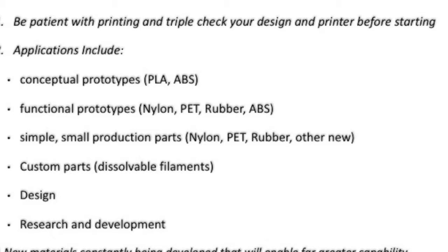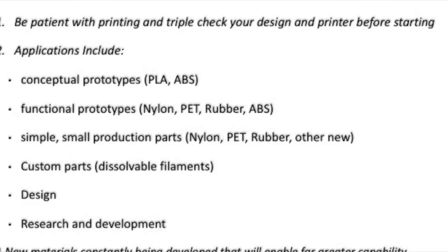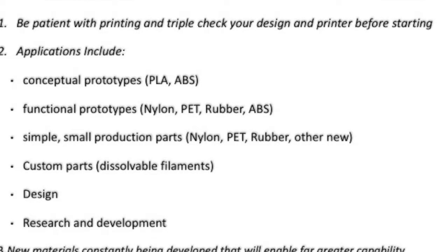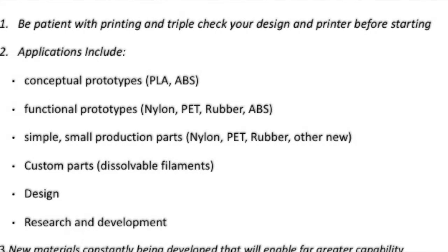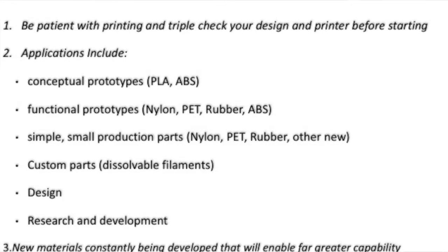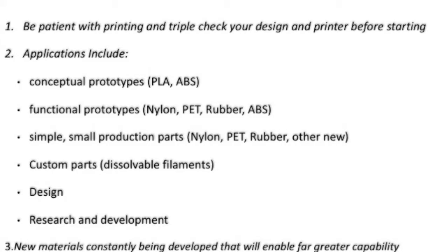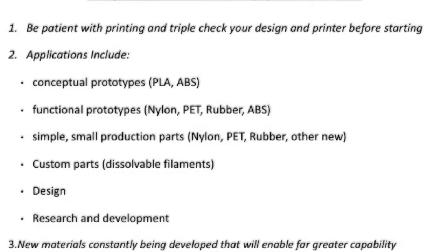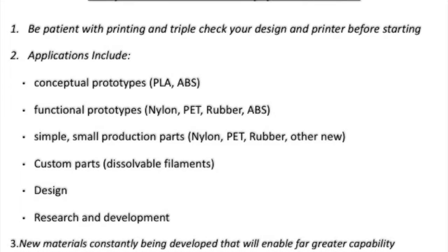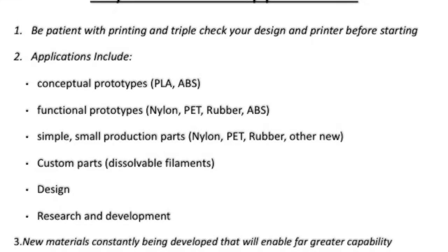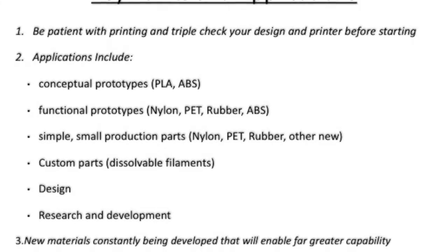There are a few key points I want to bring to your attention regarding the implementation of 3D technology into the classroom or into curriculum. One is that you always have to be patient with the printing. It can take some time to get the best print. It can be trial and error. We have to always triple check things from beginning to end. We also have to make sure that we're using the proper material for the specified application, be it conceptual prototypes, functional prototypes, or things on a small scale.